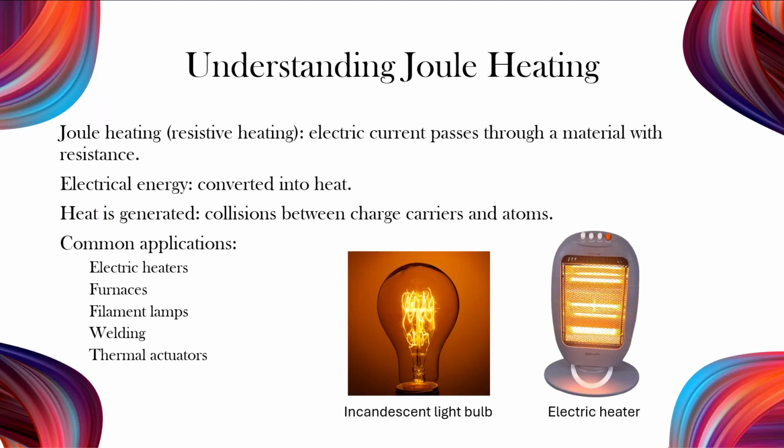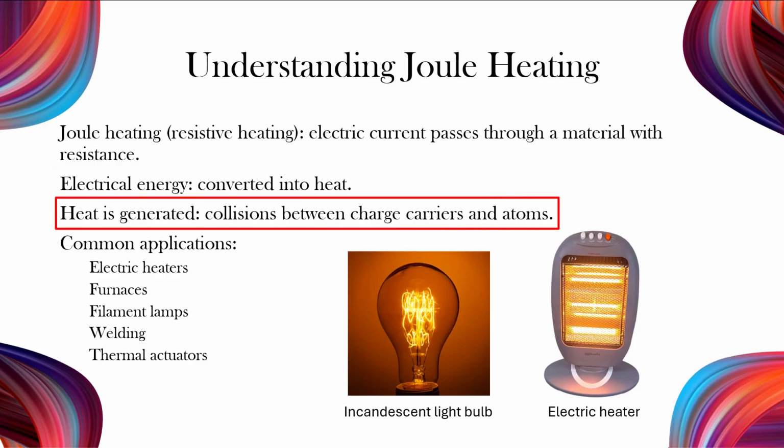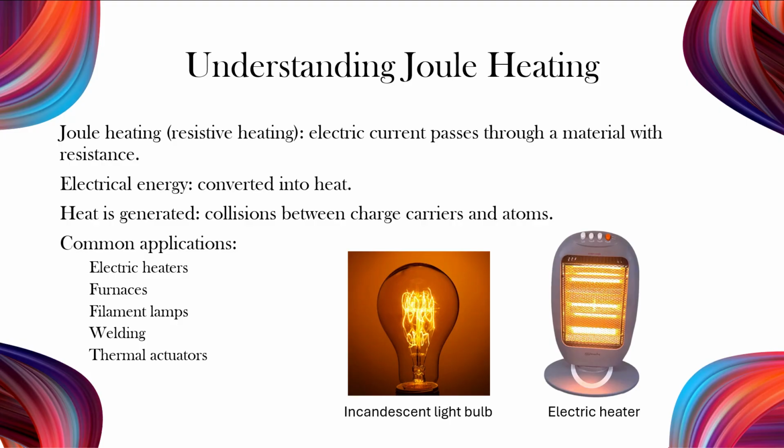Joule heating, sometimes called resistive heating, happens when an electric current passes through a material that has electrical resistance, and part of the electrical energy is turned into heat. At the microscopic level, this heat is generated because moving charge carriers collide with the atoms of the material and lose energy. We see Joule heating in many everyday and industrial applications, such as electric heaters, furnaces, filament lamps, welding systems, and thermal actuators, where electrical energy is intentionally converted into heat for practical use.